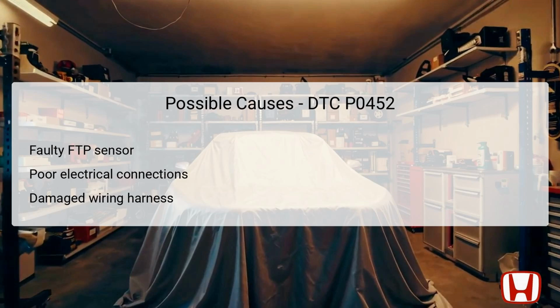Furthermore, a damaged wiring harness or broken insulation around the wires can lead to shorts or open circuits, which may result in low voltage readings. It is crucial to thoroughly inspect these components before proceeding with replacement to ensure a correct and economical repair.